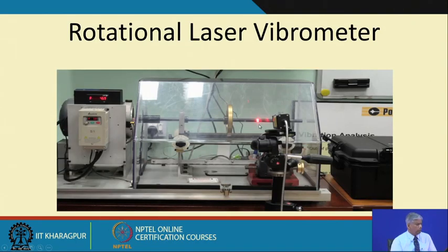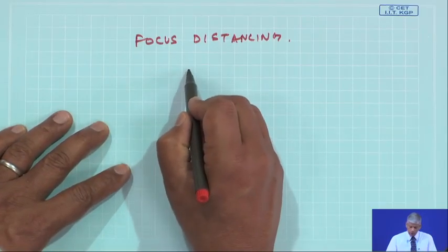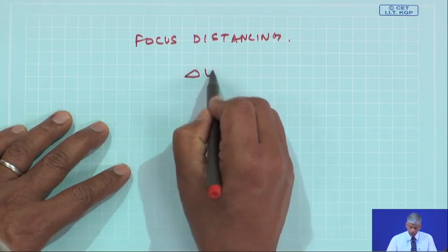Yeah. And here if you see the zoom picture, you will see two dots. This corresponds to those two laser beams which are being put on the shaft. So, you can very easily measure the speed, and actually in many condition monitoring it is not the mean speed, it is the fluctuation speed.